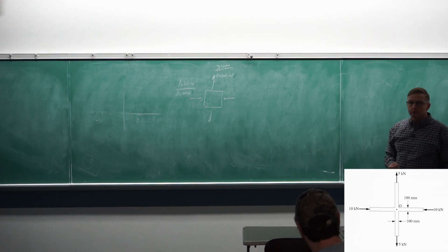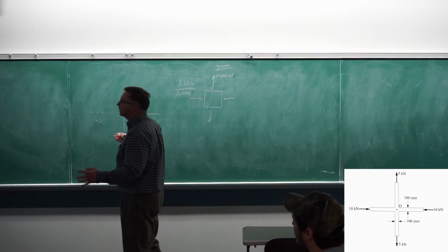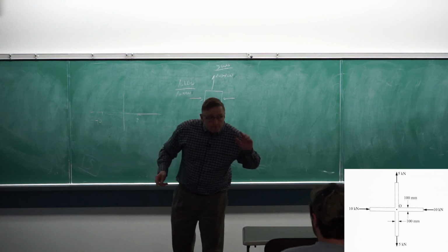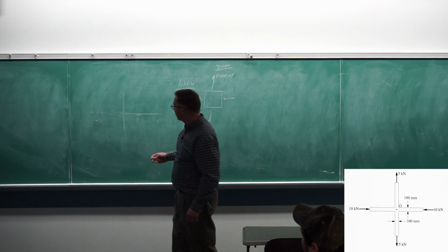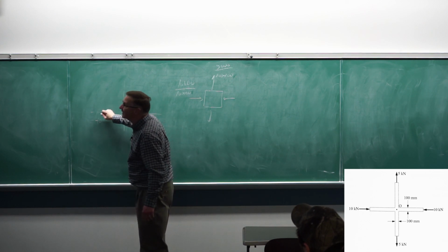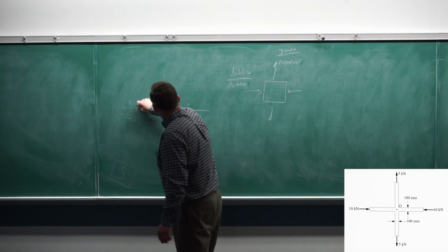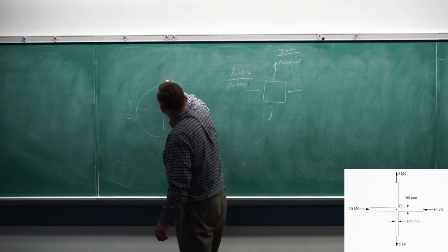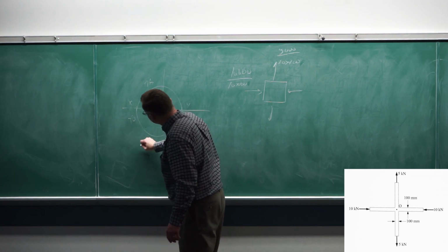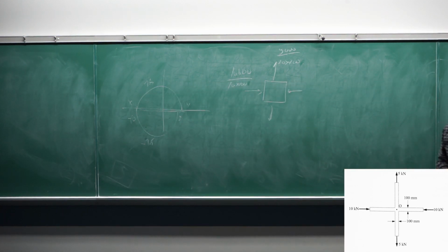But if you're floundering... So doing it the Mohr's circle way gives us negative 7.5 as well. Okay, so they're asking for the maximum shear stress. Well, remember that's the 7.5 anyway. It would just be 7.5. It's the same magnitude whether it's positive or negative, because Mohr's circle puts you at minus 10 for the x direction and positive 5 for the y. This is your diameter, this is your radius, and the radius here is 7.5, positive 7.5 here, minus 7.5. But that's the same shear stress. Yeah, okay, that makes sense. I haven't done Mohr's circle in a while.